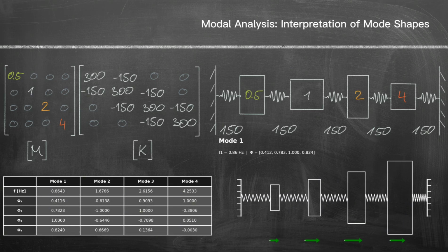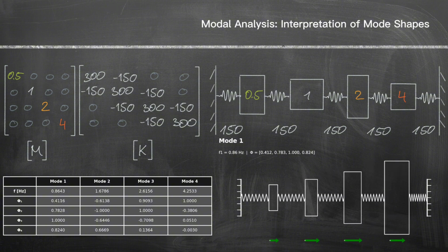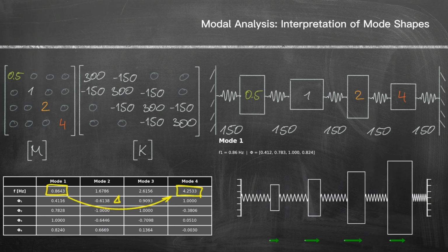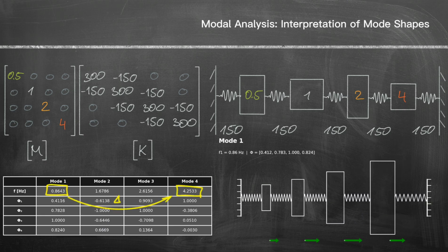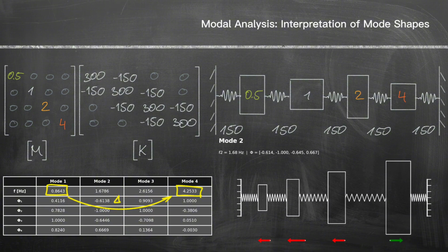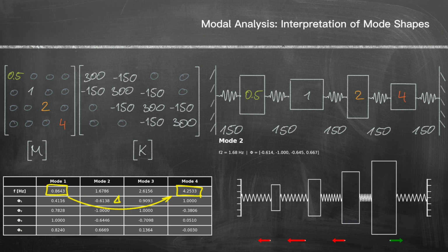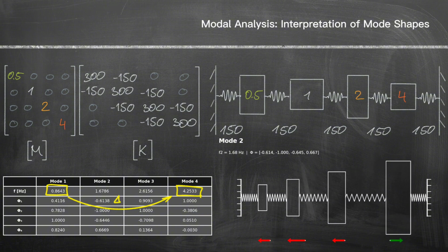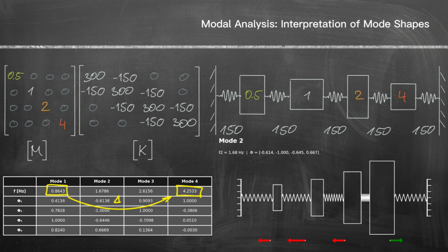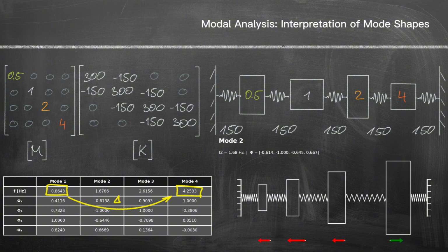Now we'll consider the spacing of eigenfrequencies. With equal masses, frequencies tend to cluster. When masses differ strongly, the spectrum spreads. This behavior can be understood directly from the ratio of stiffness to mass. Light masses connected by moderate stiffness lead to high frequencies, while heavy masses supported by the same stiffness generate low frequencies. An effective qualitative estimation strategy is to ask which mass dominates this mode, or through which stiffness path it is constrained.